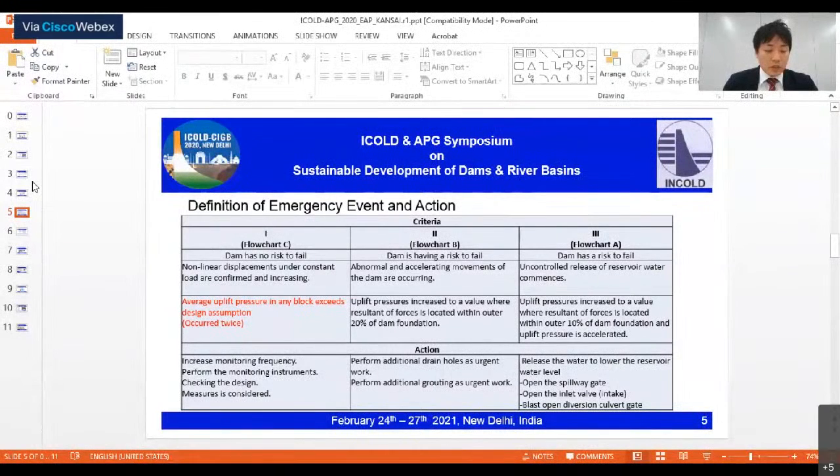twice in accordance with the guidelines set out in the EAP, and each time mitigations were taken and appropriate measures were taken. It is judged that the plastic movement of the dam foundation closely corresponds with repetitively rising and lowering the reservoir water level.